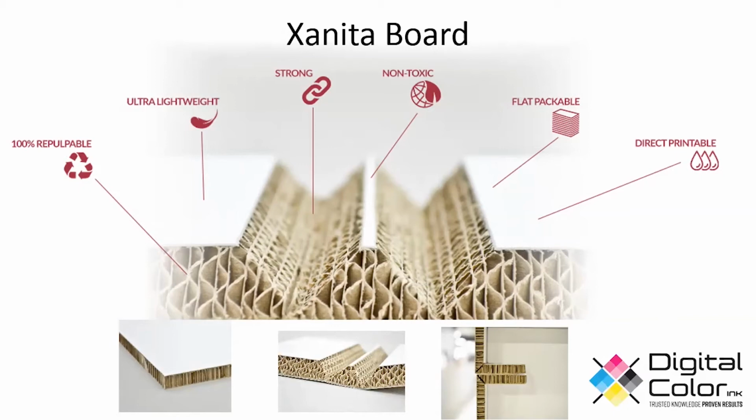The board itself, the core, the liner, the resin, the adhesive, everything in Xanita board contains no VOC, so it's non-toxic. We mentioned that it's flat packable and direct printable. So Xanita board is a great sustainable product in itself, but it's strong enough to allow you to build load-bearing three-dimensional structures. Through multiple V-cuts, single V-cuts, forming right angles, you can create a wide variety of different structures. And that liner and that core allow the V-cut to stand up over and over again without crumbling or losing any of its strength.